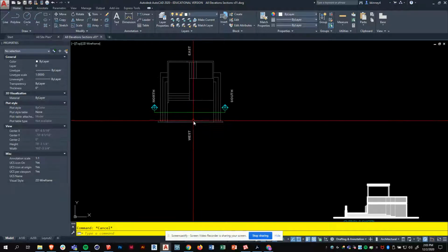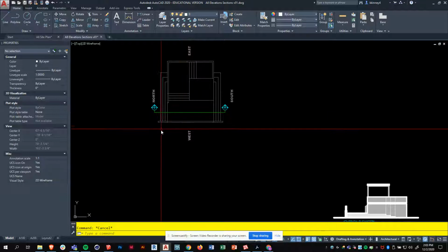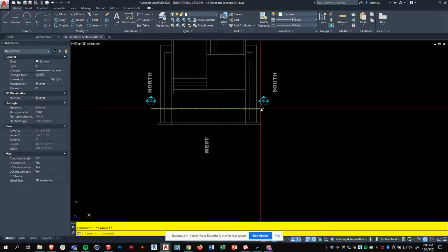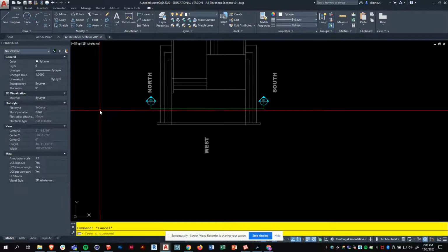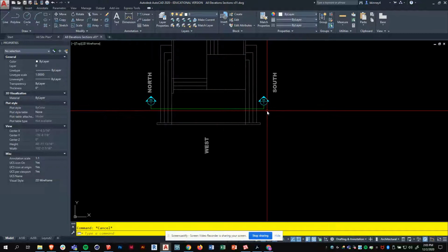Okay, so let's use construction lines first. So here's a good way to, let's just draw the section cut. If I'm coming along here, I'm at the ground plane. Then I come here and I hit a step. So I come up 6 inches, come over, come up 6 inches, come over, come up 6 inches, come over, come up 6 inches. I'm on level 1 and then down in the same way.